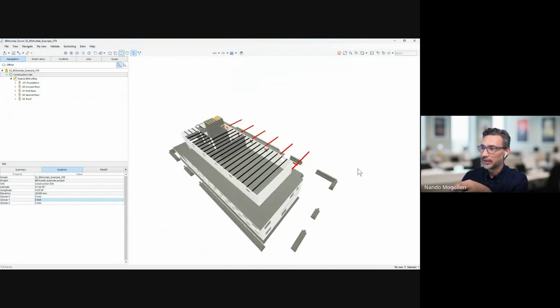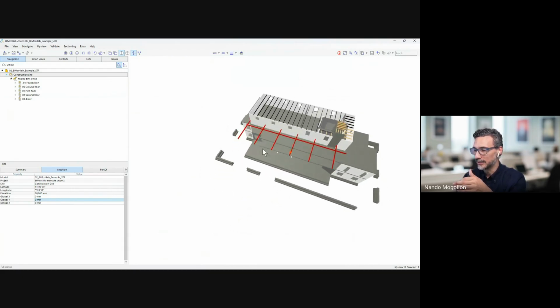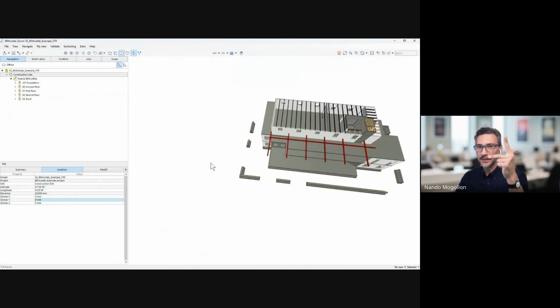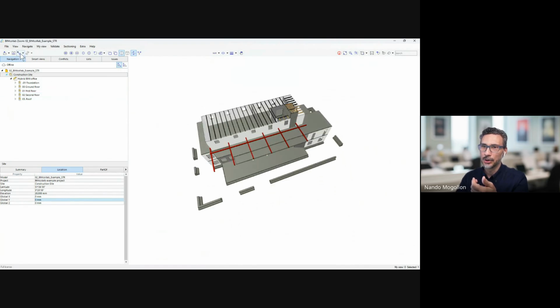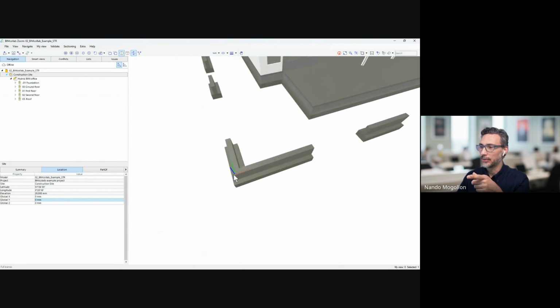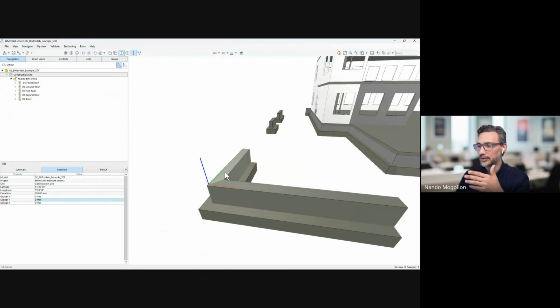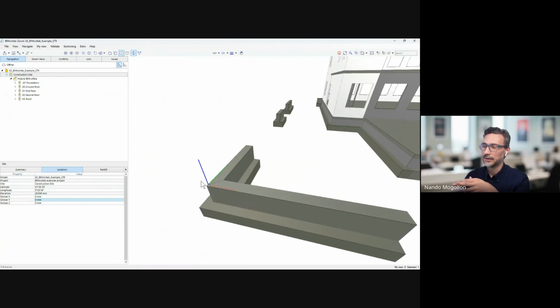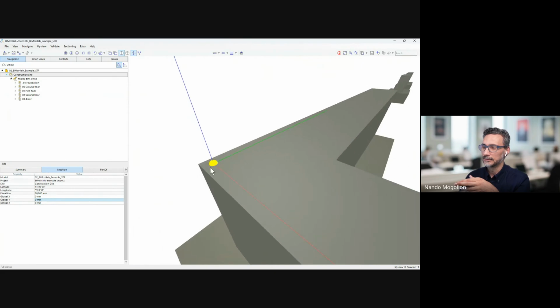Cool. Now, even if that's the case, how do I know what the orientation is? Where are X, Y, and Z? Because I don't see the typical 3 axes. You can see that, but you have to call it up. The way we normally do that is you go into View and click on Show Model Origin. Once you click on that, a 3-axis origin will be displayed in the model. Coincidentally, this was set up on purpose to be close to the corner of the building right there.